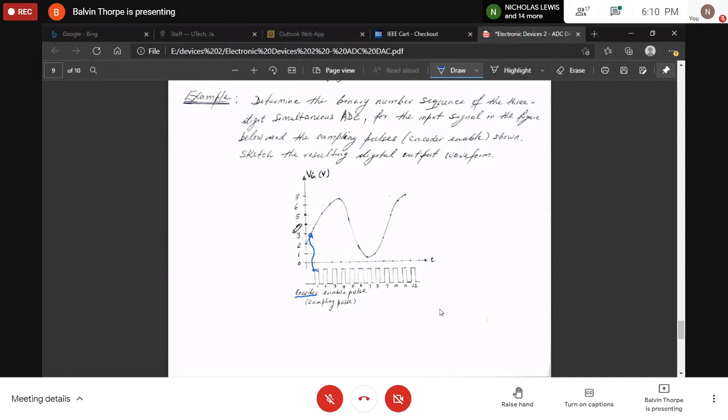It's going to put out a voltage when the input voltage is compared to the reference voltage and it is high. Otherwise, these are going to be low. So as far as the comparators above this point are concerned, the values are going to be 0. Because at this point, you see, there's no signal here, only from here going down. So at that interval, it is 3.